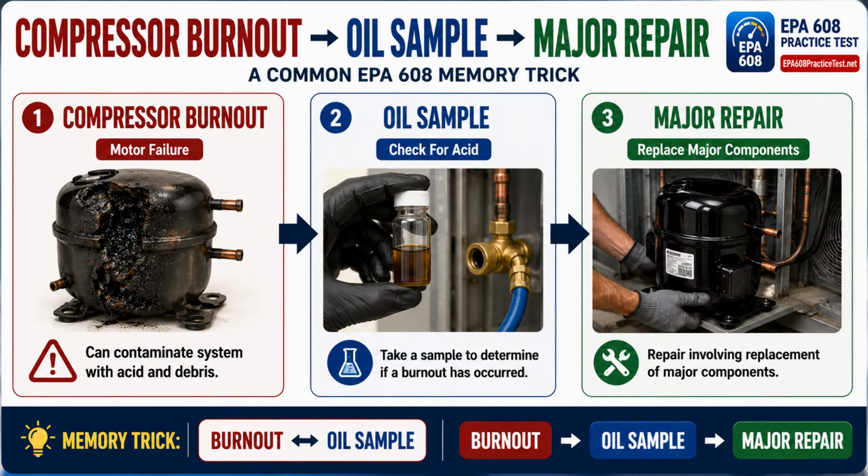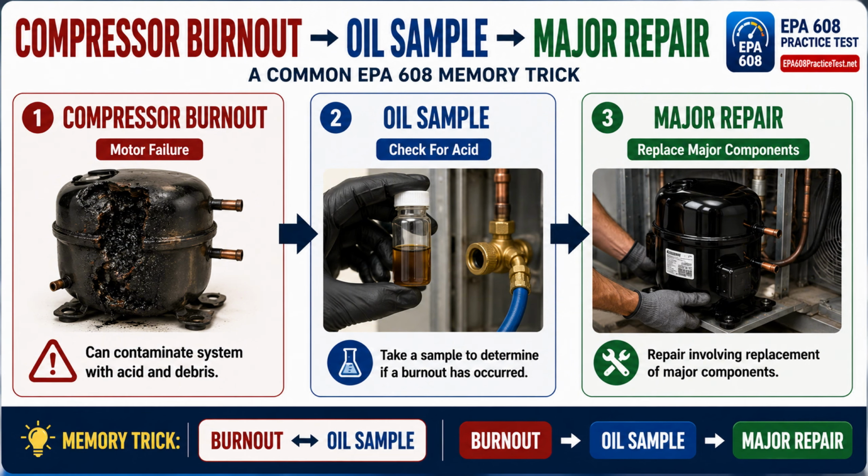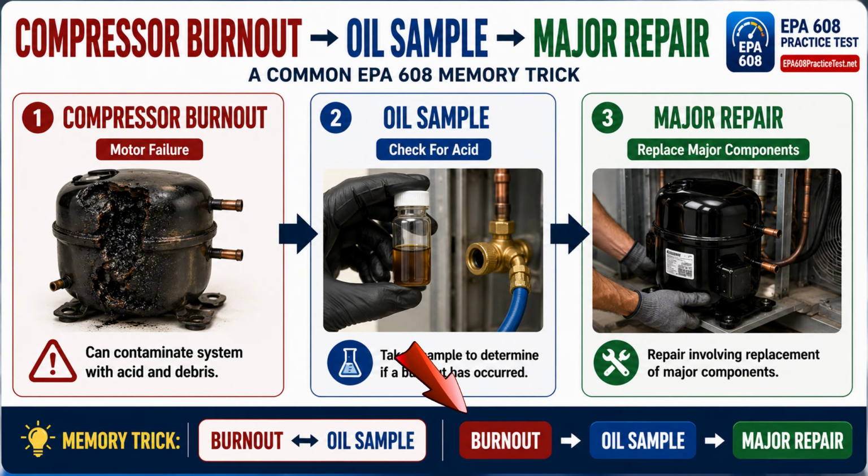System repairs. Compressor burnout is a serious compressor failure that can contaminate a system with acid and debris. When a burnout is suspected, technicians take an oil sample to check for contamination. If major components need to be replaced, the work is considered a major repair. For the EPA exam, remember this common connection. Burnout, oil sample, and major repair often appear together.